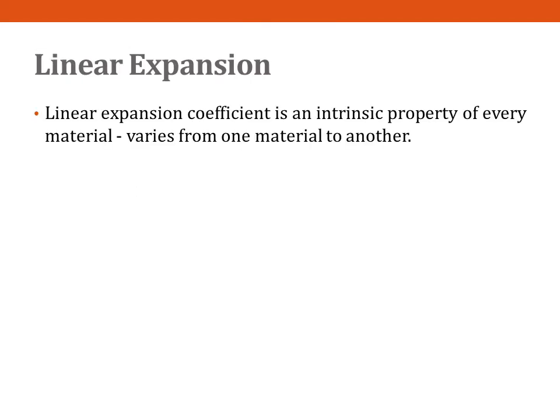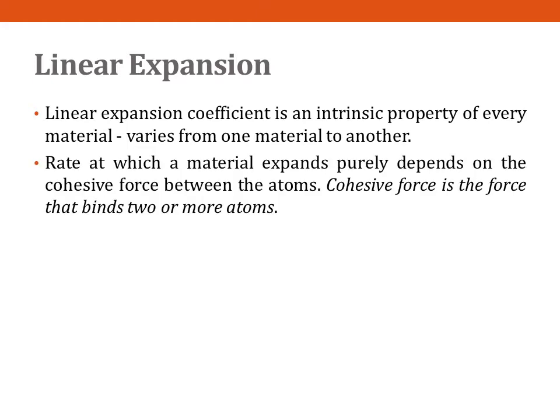Linear expansion coefficient is an intrinsic property of every material and it varies from one material to another. The rate at which a material expands purely depends on the cohesive force between the atoms. Cohesive force is the force that binds two or more atoms together, and this cohesive force resists the atoms from getting separated from each other. The greater the cohesive force, the lesser the expansion of the material.